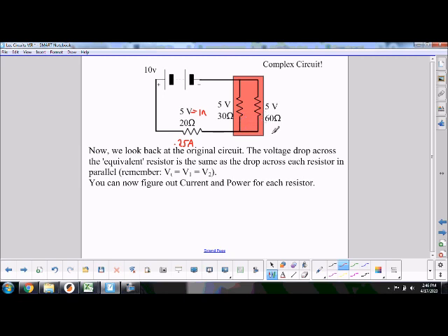But remember, we did know that this imaginary, illusionary, fictitious resistor was also 20 ohms. And it had 0.25 amps going through the imaginary, illusionary, fictitious, not really there, but we'll pretend it is the resistor. Which means the voltage around that imaginary 20 ohm resistor was, you guessed it, 5 volts. So that means in this region, it's 5 volts.